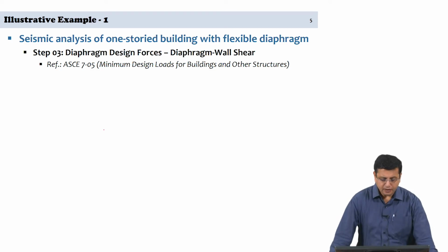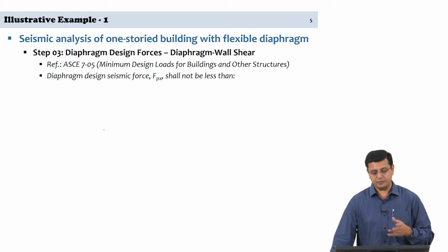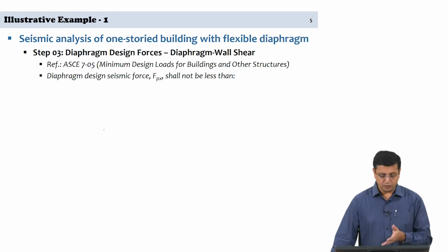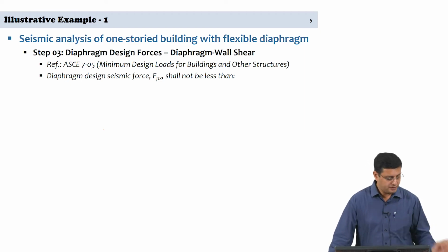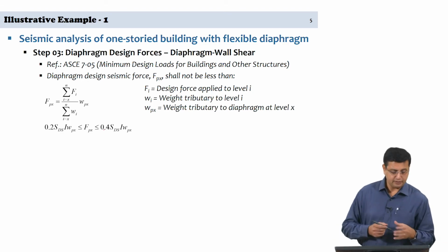So, what does the ASCE 7 prescribe? The diaphragm design seismic force, notation here is Fpx, shall be estimated as given by this equation.